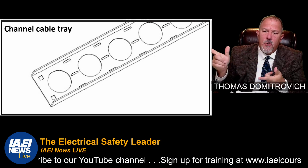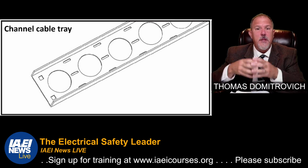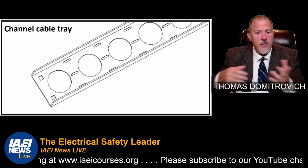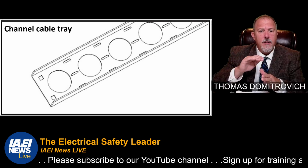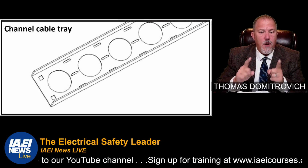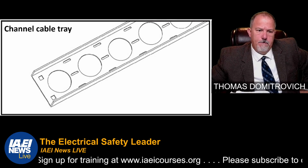In all of these holes that you see where you might have cable coming out, they'll have bushings that should be installed in there because you don't want any edges to damage your conductors. So be very mindful anytime you take a conductor through a cable tray opening, like holes like this. Look for those grommets that can be placed in there.